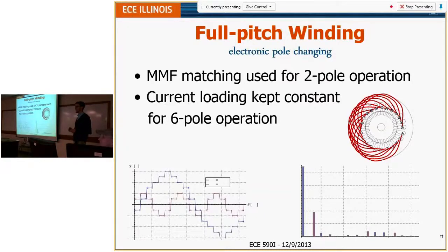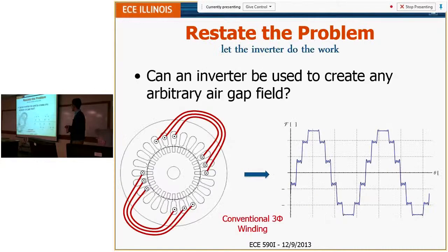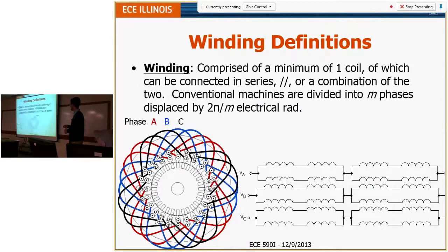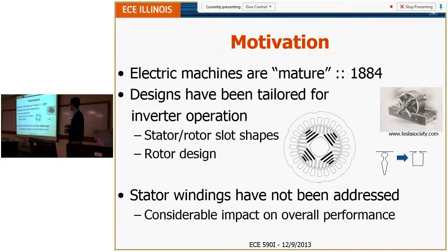The mechanical? Yeah. So you do a mechanical analysis on the rotor. Professor Klein mentioned in class the other day that this machine here is called the IPM machine, where you have chunks of magnet. When you spin it fast, the centrifugal forces are pushing those magnets outward.